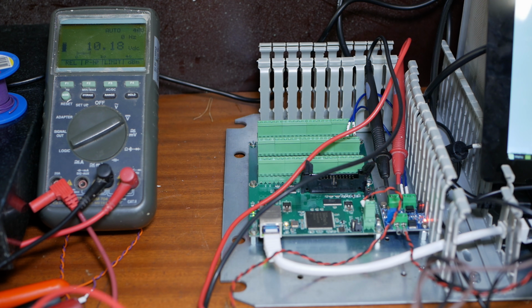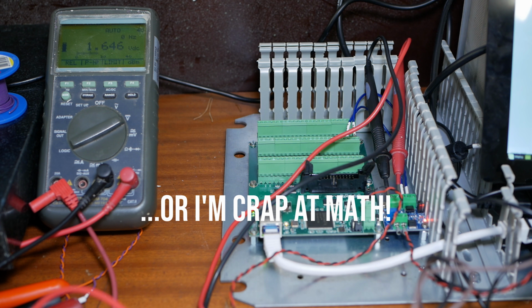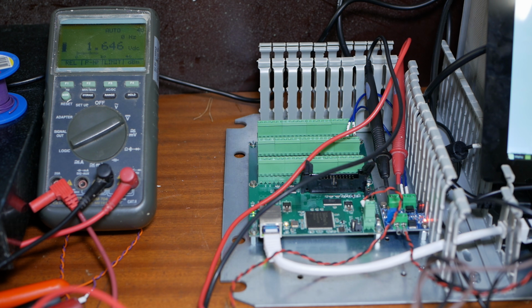Okay, let's try a different value. Let's drop down to 1/10, which would be 271. Should give 1 volt. Okay, it's a bit high, it's 1.3. But obviously the system is now working. Let's go for 342, which would give us 2 volts. Okay, it's not very linear down there. 1350 RPM should be 5 volt. Once again, it's a little bit high.